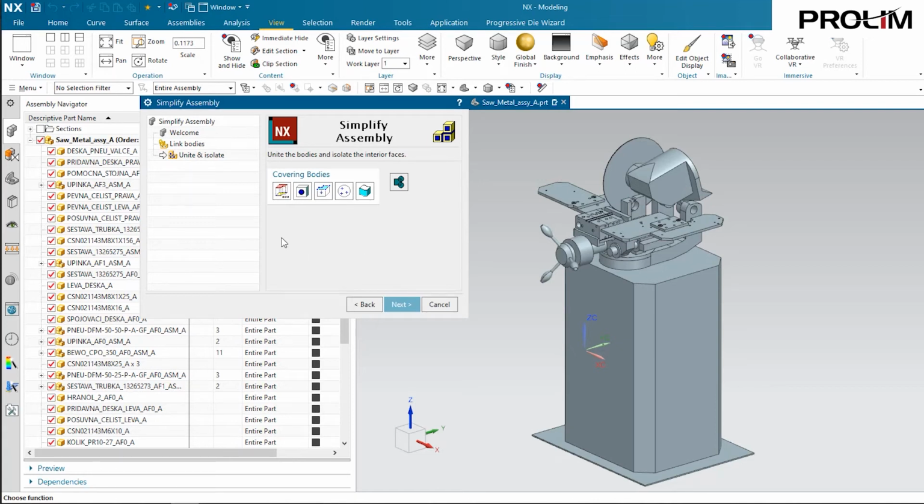Now, once you get to this step, it's going to give you the option of selecting which tools you want to use. The tools available are the Extrude dialog, the Plug Circular Holes, Body from Outline, Bounding Sphere, Body from 3D Profile, and finally, the Unite All. Like I said earlier, we're just going to focus in on this Plug Circular Holes for this assembly.